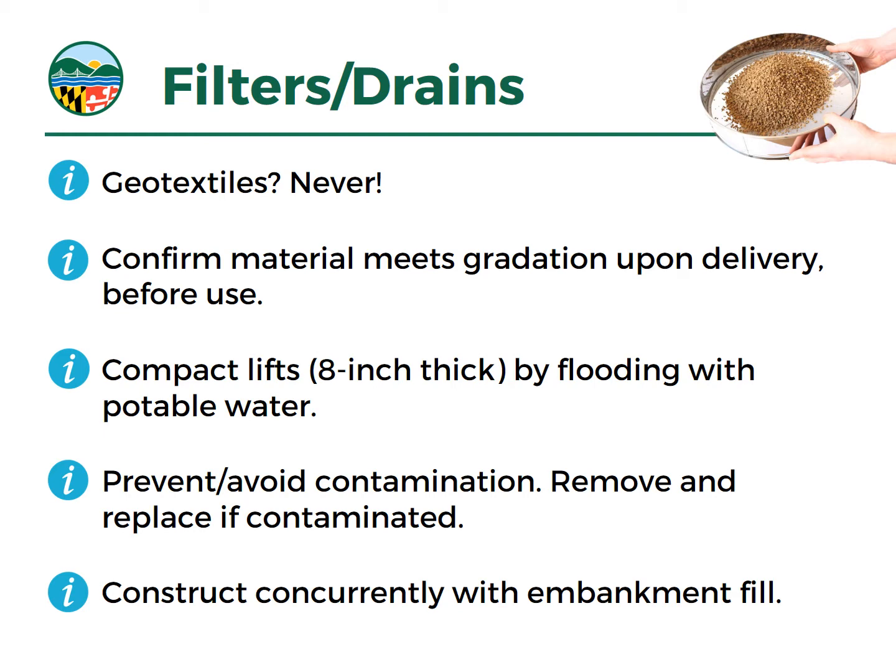So can you have a geotextile maybe separating a superficial riprap layer from the underlying soils, where the riprap might be providing like a swale along an abutment groin or along the upstream face? Maybe yes. Would a graded filter below that riprap be preferable? Yes. But should we ever be wrapping our perforated pipes and our internal drains in geotextiles? Absolutely not.